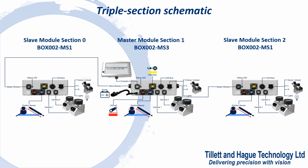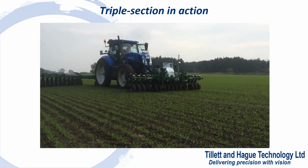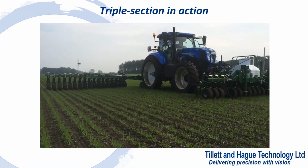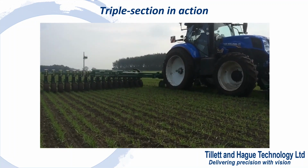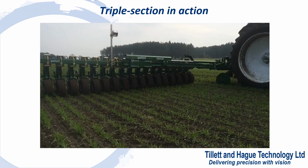Similarly, you can follow 3 independently planted belts with a triple system. This uses a master module with 2 slaves. The 3 sections can all be rear mounted, all front mounted, or split with the centre section on the front and the outer sections on the rear of the tractor. This is a particularly nice configuration from a vision guidance perspective, as it gives a totally clear view for all 3 cameras, thus providing the best possible performance.